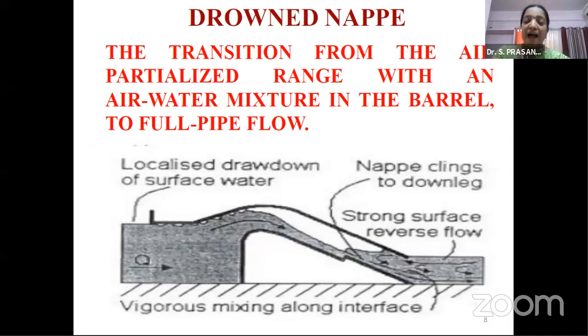Still further, when you have an increase in the flow, for all these three cases which we have just looked upon, the water has not moved above the lip level of the siphon. It is still below the lip level of the siphon. Now, with a further increase in the flow, because the water is getting discharged onto the downstream side, there is a space for the air and water to have an interaction in between. This is something which we call, in terms of simulation, multi-phase analysis or multi-phase flows. That means air and water is going to have a mixture of it.